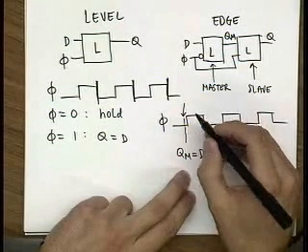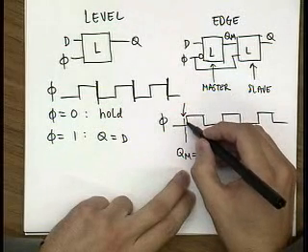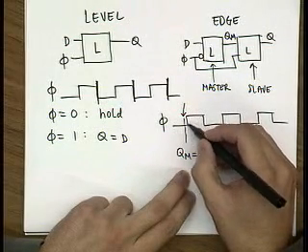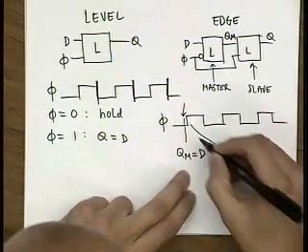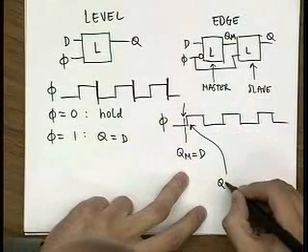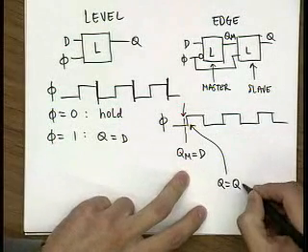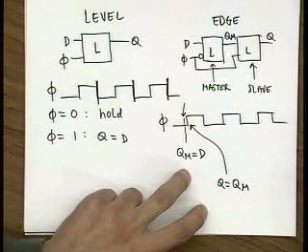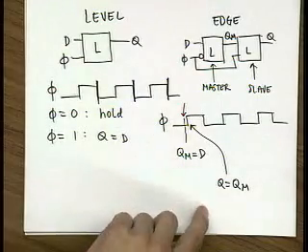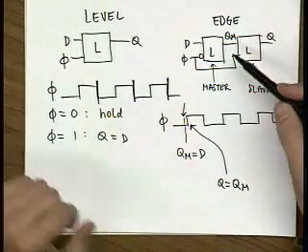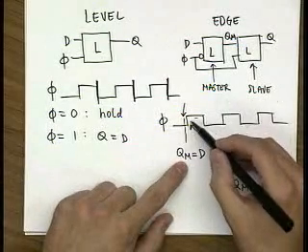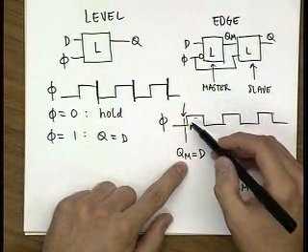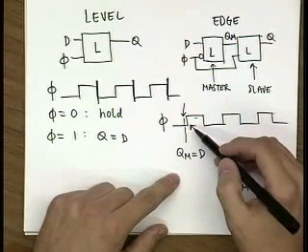But now that happens actually at the edge of this clock, because after this point you basically have that Q copies whatever was at the output of the master latch, correct? So slave copies that. And now the point to realize here is that since the master latch is in the hold mode over here, output of master latch can no longer change.